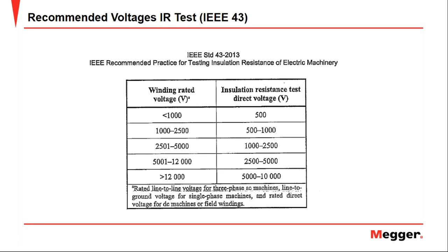We have to always do the measurement in the same condition in order to be able to compare the measurements. The equipment does the capacitance test at a voltage that is fixed in the equipment, so we can compare the measurements in the future. If we do the measurement with a bigger voltage value, obviously the capacitance reading is going to change.